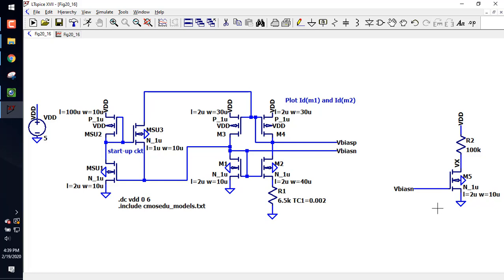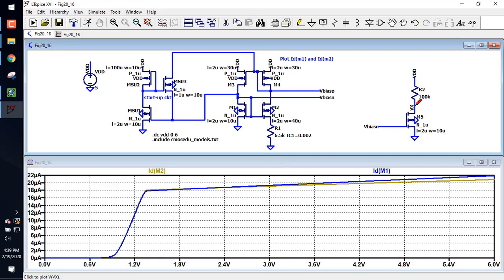And then if I start to sweep VDD, what's going to happen to Vx? It'll start going down linearly, or if I'm sweeping VDD up, it'll start going up. That's the temperature coefficient of the resistor. So let's hit run, and then let's plot Vx.